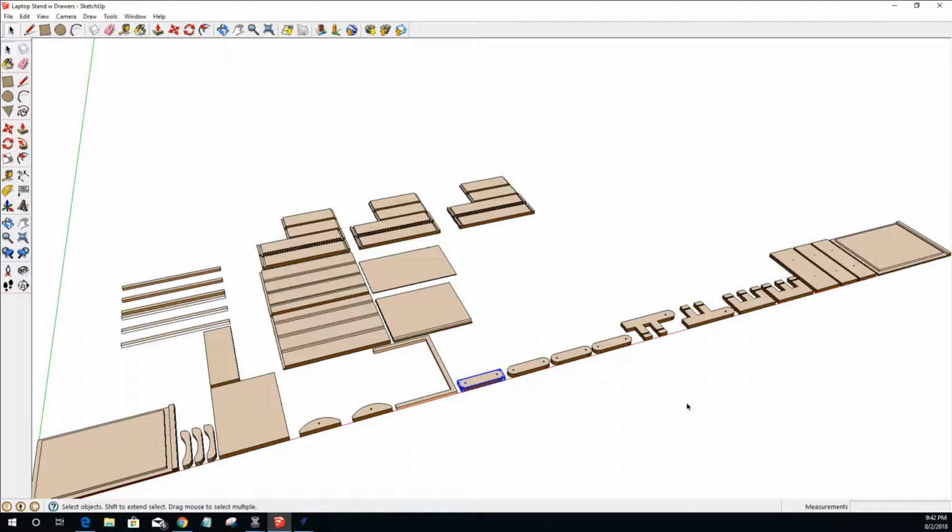This class tonight, even though we just recreated everything that was already given to you, was a training in how you would approach it in case you want to start using SketchUp to create some designs to bring into Vectric. How you need to go through and identify the vectors you don't need and get rid of them, and then create the toolpaths on your parts the way they need to be created.